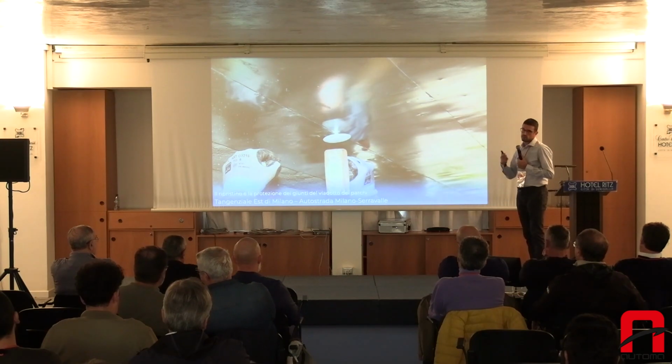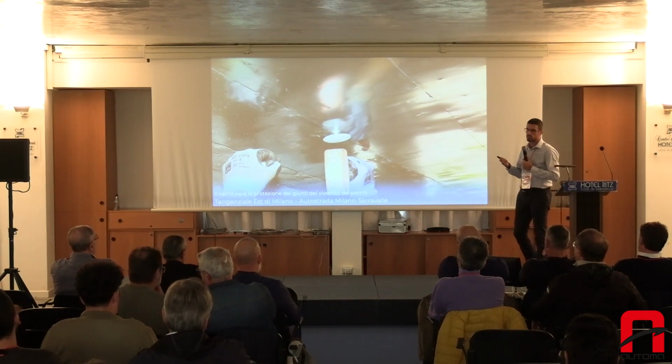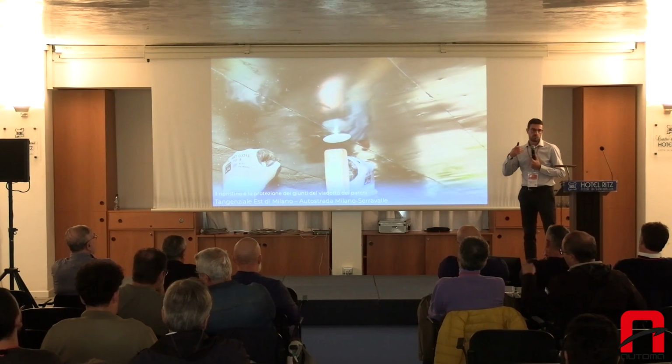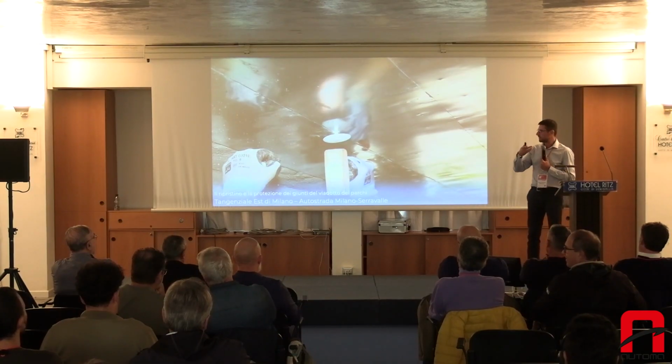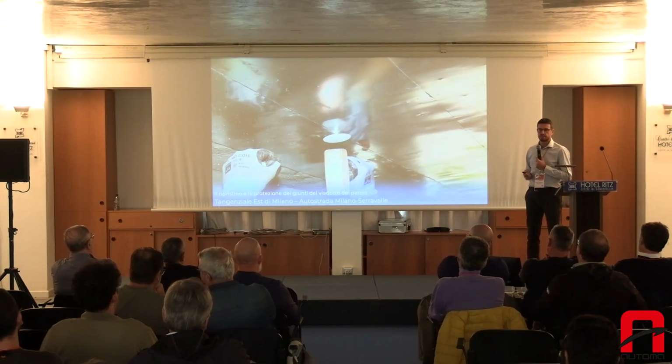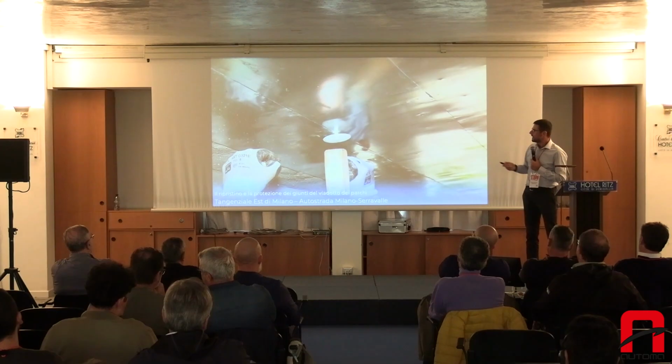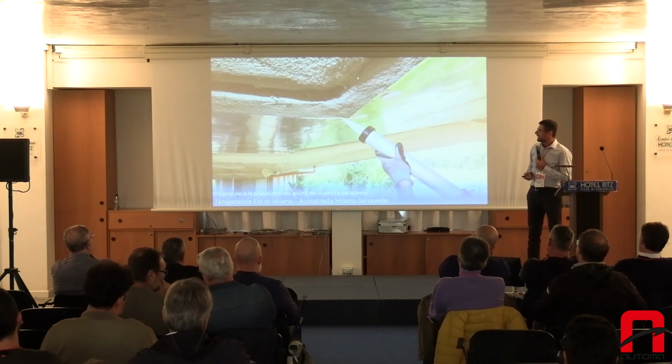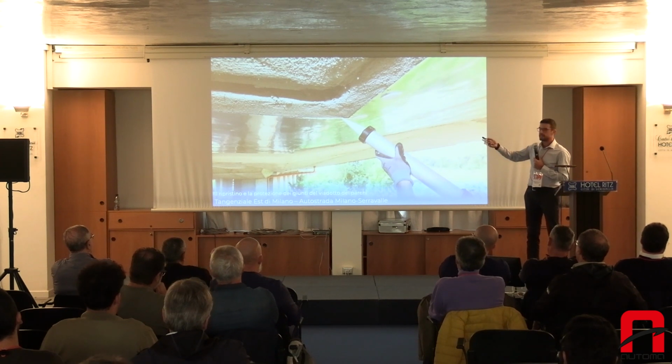You remember I suggested that you should mechanically fix the sheet because we know that the viaduct can be subject to vibration because of the vehicles that use it. So the mechanical fixing element is very important.